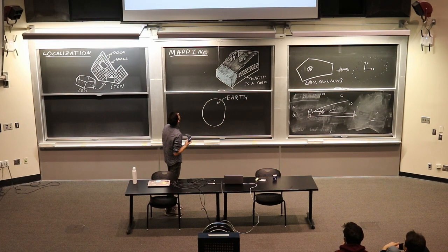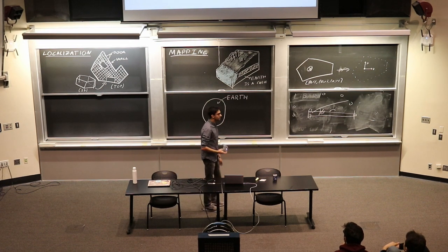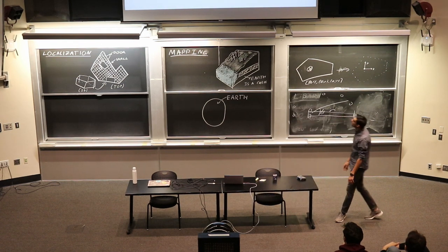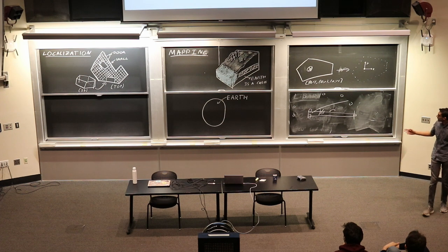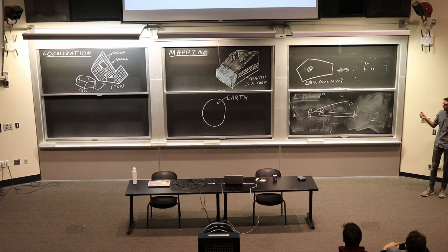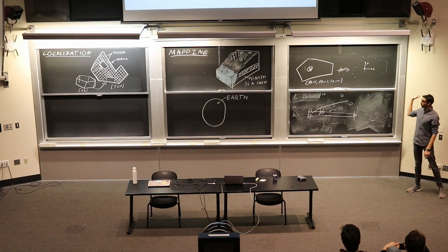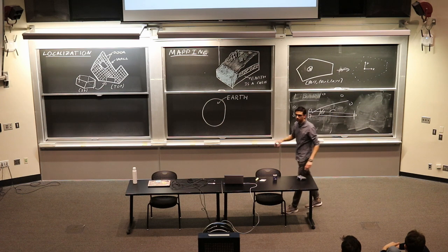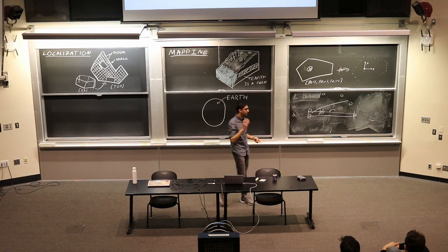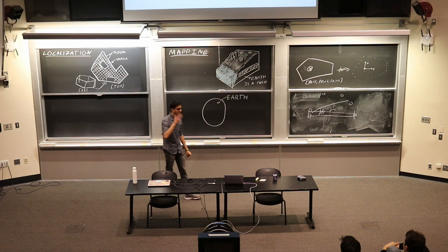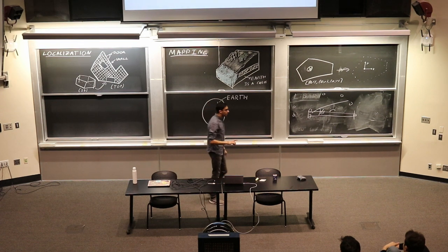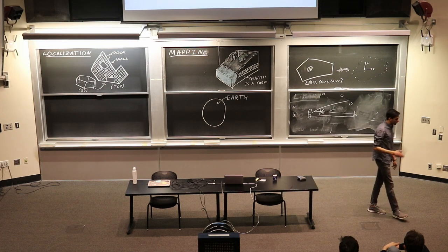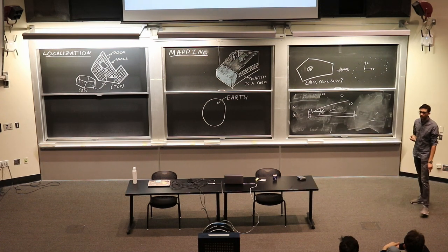Okay, yes. LiDAR is literally a time of flight distance sensor that spins. There's really not much more to it than that. The only distinction I'm going to make is instead of getting one value out of it, you get this point cloud. And depending on the number of channels your LiDAR has, channels meaning the number of lasers it has on it, some LiDARs have up to 16 lasers. The one you have has one. So you have a one-channel LiDAR. The 16-channel LiDARs give you hundreds and thousands of points per scan.